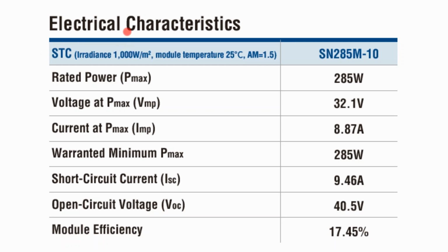This irradiance value of 1,000 watts per meter squared jumps around too. It increases at high noon when the sun is not going through as much atmosphere, and decreases throughout the day. And then there's the atmosphere itself, the haze, the humidity that can diffuse the light. At any rate, what we do in the design aspect is we look at these extremes and design off open circuit current, open circuit voltage, full power. But we go back to PV Watts to see what typical system performance will be like.